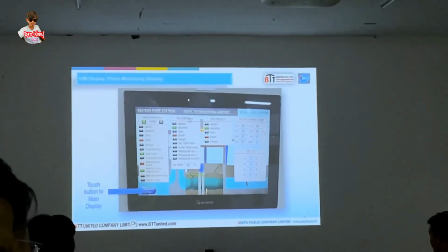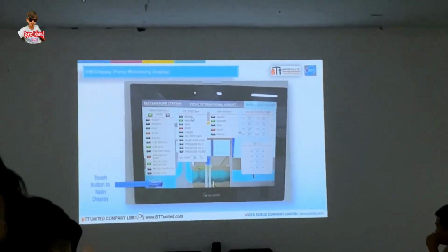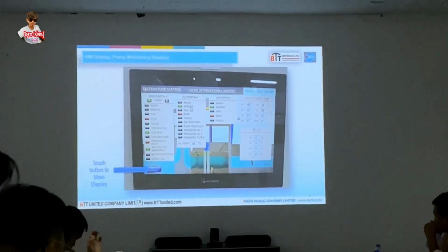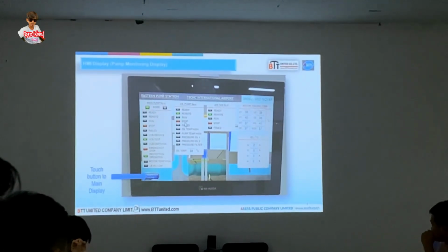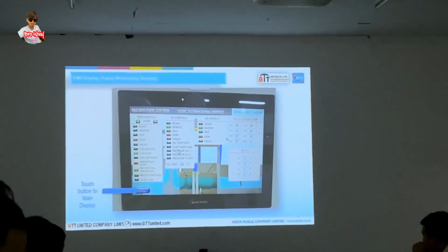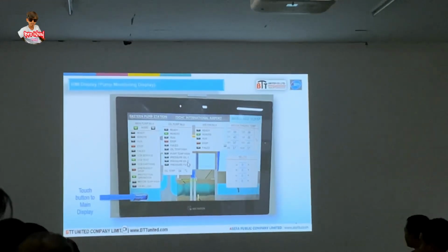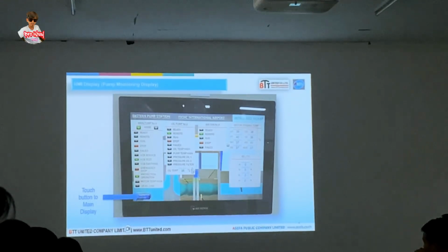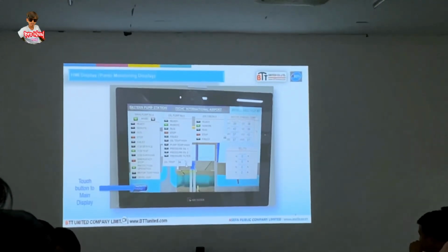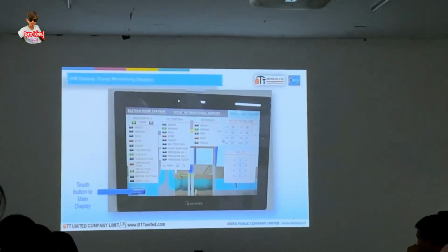You also have the monitoring system of the oil pump, which shows whether it's ready to start, remotely controlled, running, stopped, failed, or has an oil temperature alarm, pump temperature alarm, pressure oil alarm, and pressure filter alarm, as well as the oil temperature sensor sending the signal in for temperature monitoring.